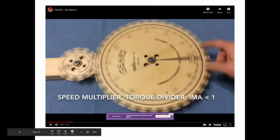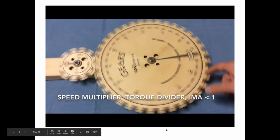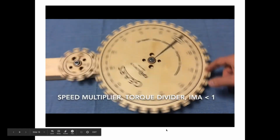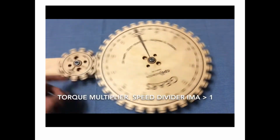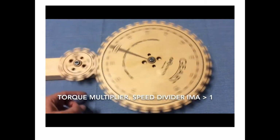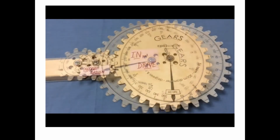If the big one is the input driven by my hand and the small one is the output, this is clearly a speed multiplier because the output is moving faster than the input. Switch it up. The drive gear is the small one. The driven gear is the big one. It's moving slower, so this machine multiplies torque.